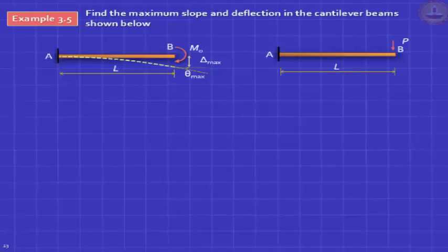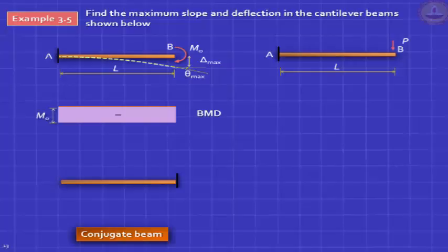So you know from the direction of moments itself, that beam is going to hog. If that beam has to go up in single curvature, it's going to sag. Very simple. The only way hogging can be done is in this manner, just as when you apply the constant load here. So your answer is correct. I wish you gave this answer.